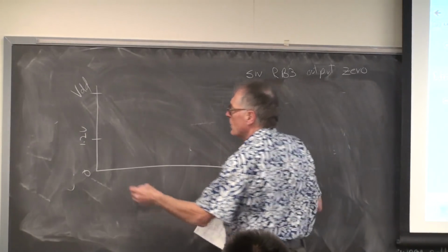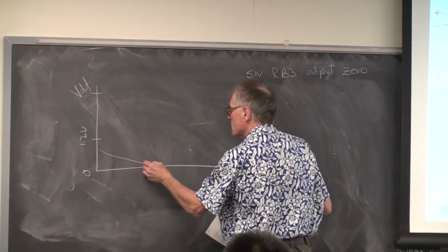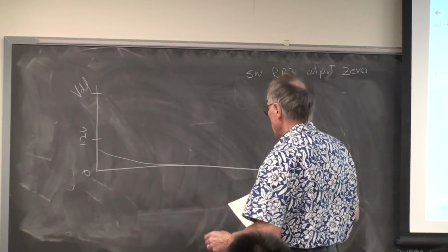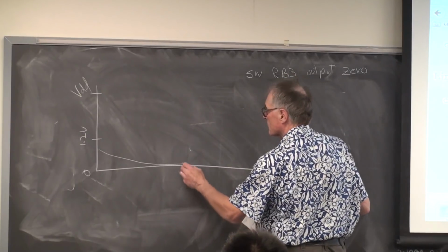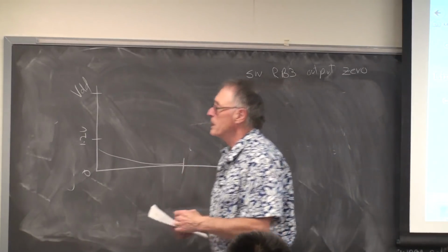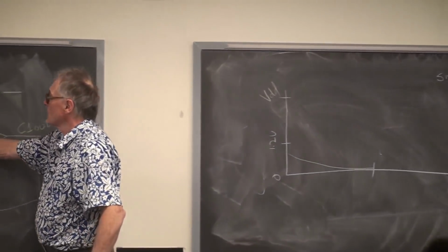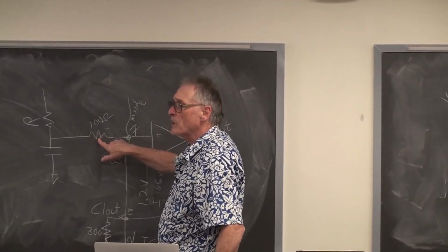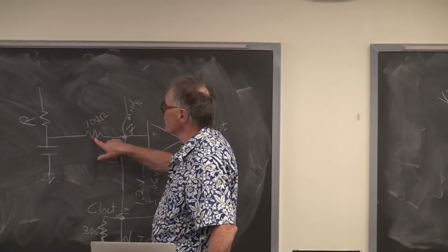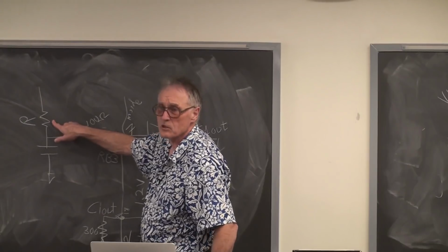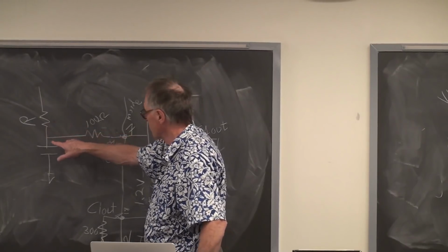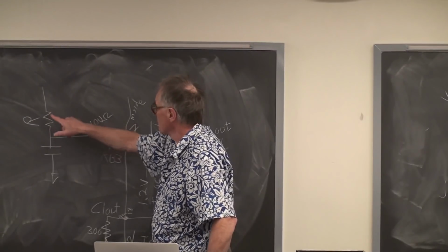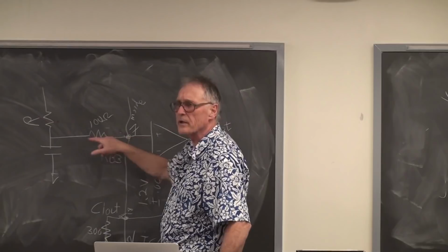When we do that, we will discharge RB3, pin 7, towards 0. Because now this pin will be held at 0 through 100 ohms. If I want to get this near 0, though, R has to be much, much larger than 100 ohms, because this is a voltage divider. What I care about is the voltage on the capacitance, right? So we want at least a 100 to 1 voltage divider here.